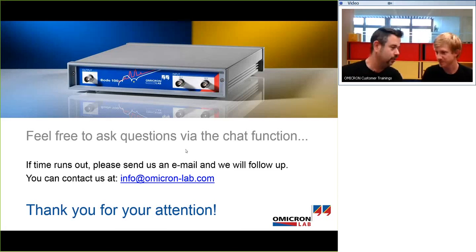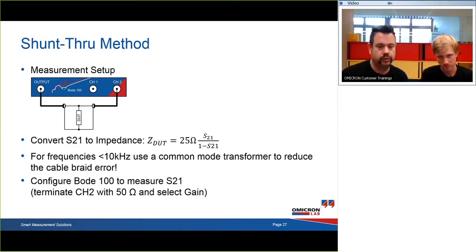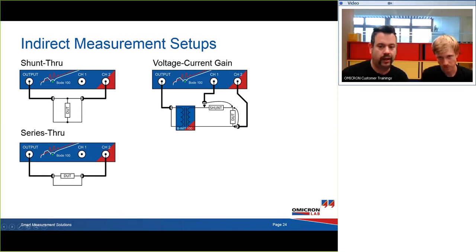Yeah, you can also mention that this application note is written in cooperation with Würth Electronics. So we already got the demo board for this measurement, and we will measure the input impedance of a power supply with different methods. We will use the indirect voltage method that was shown earlier, where we use a current probe, a shunt resistor and the device under test.